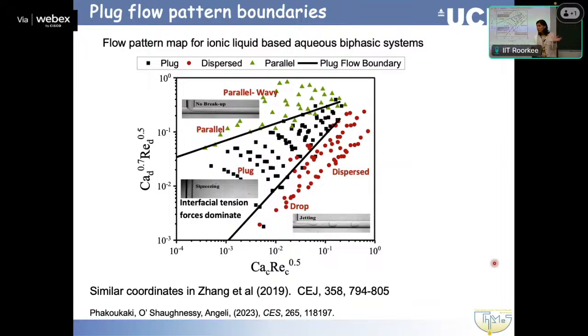Often, that's what happened also in gas liquid flows. There is a lot of data for atmospheric pressure gas liquid flows, so basically, I think predictions are good. Once you start going into higher pressures, for example, then discrepancies start appearing. The same will happen here. The data is building, but of course, the more common systems, organic solvents, kerosene or water, would have more data. Once we get into more complex different fluids, then of course we'll have to check.